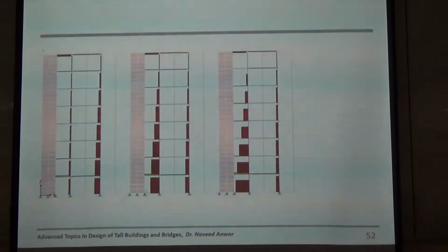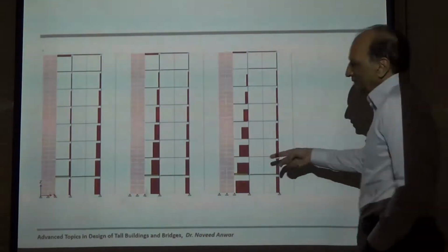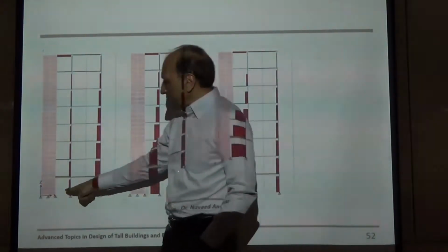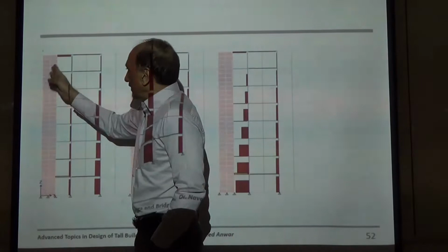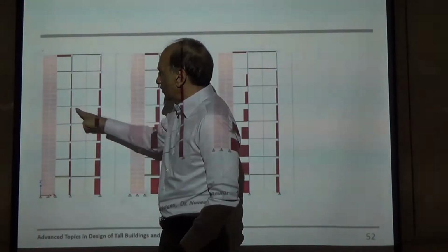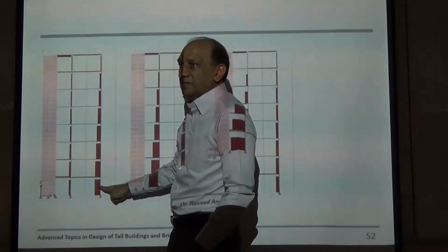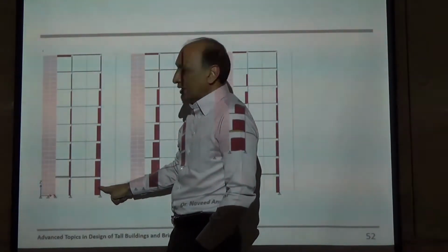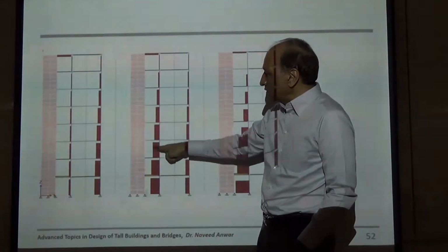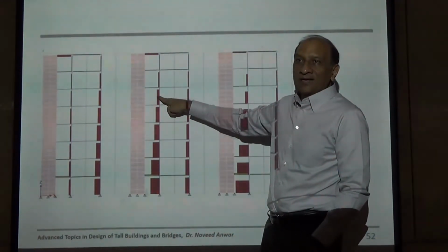And that is the axial force in the column. Now this is very interesting. You can see from here that when you apply the lateral force, this column has almost very small axial force, but this column has a large axial force here, compression here. In this case, when we increase the size of the beam, this column starts to have larger axial force.